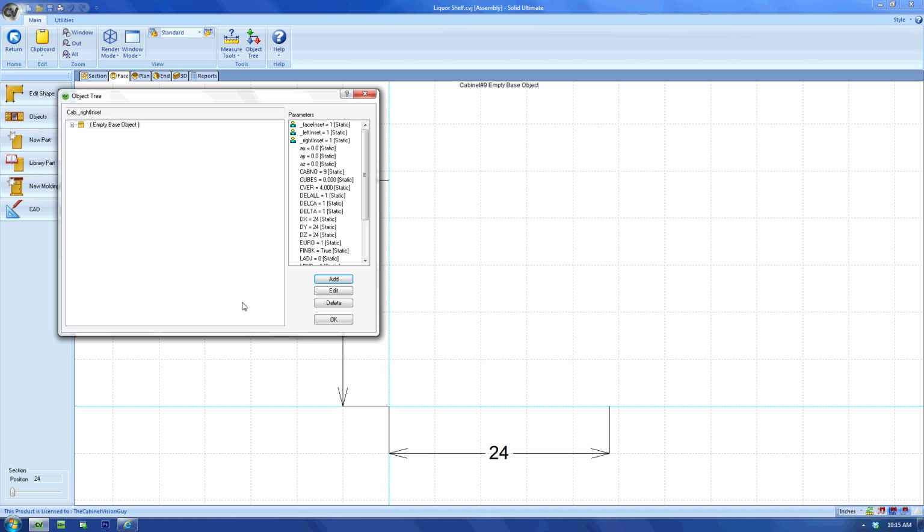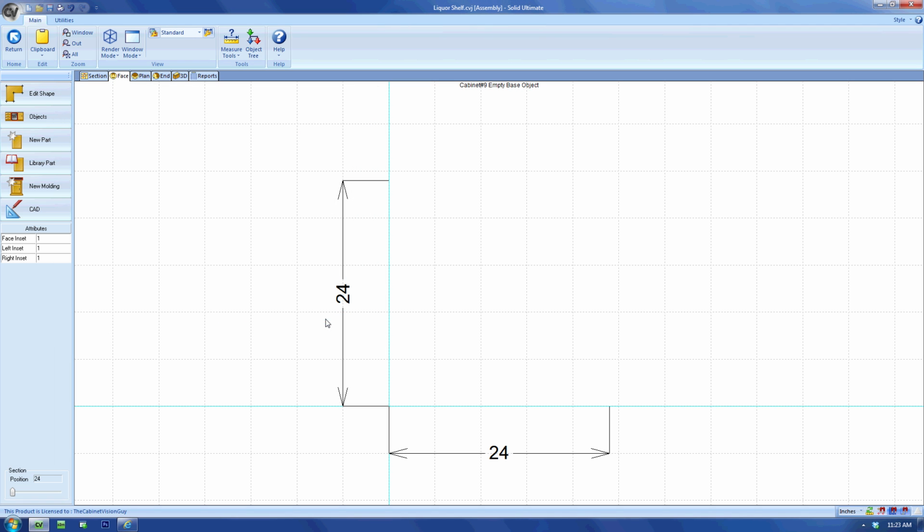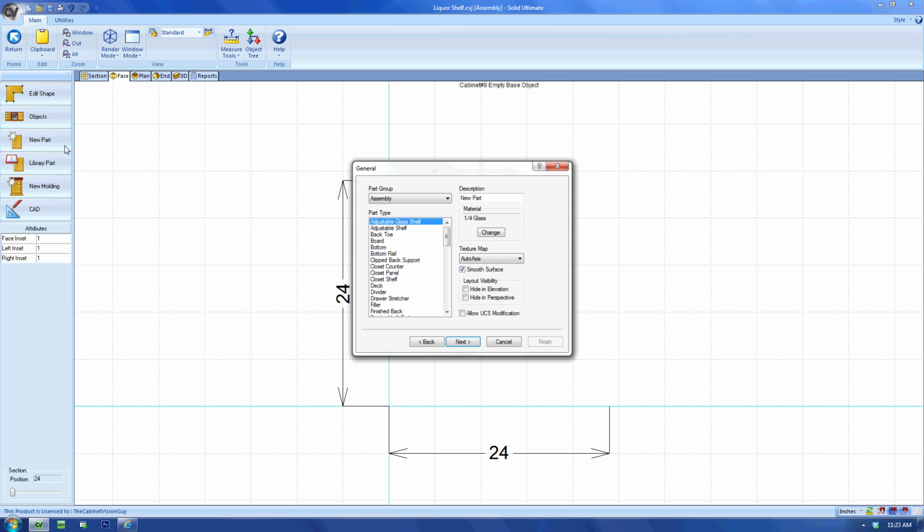With those three parameters, I have more control over the shelf than I normally would when building an object from scratch. The next part of our planning is how to actually build the piece. Typically, you would start with the substrate and build outwards. Well, for this, we want to build from the outside in. I want to have a skin for the left and right sides, as well as a skin on the top. And I want to have a nosing around the perimeter of the shelf, so we're going to start with those items first.